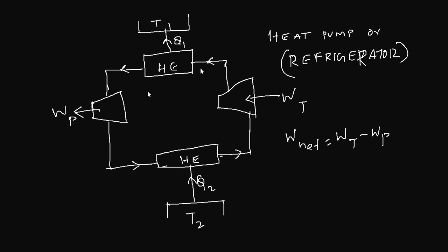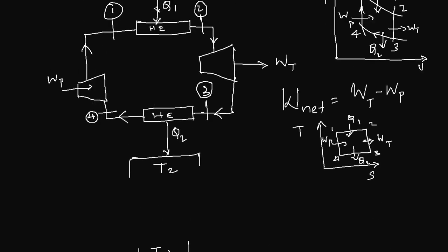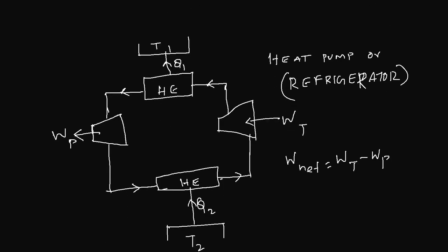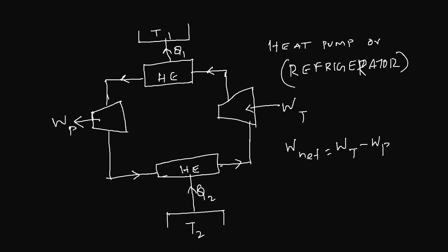Again, this is a reversible process, a reversed heat engine. This is the ideal case. This is not practically possible, but it is possible to produce a refrigerator and heat pump with losses, which means it is not reversible. Obviously there will be heat losses and friction losses, etc. But the concept of the heat pump and refrigerator originates from, and can be described from, the concept of the Carnot heat engine. So we have the Carnot heat engine and the reversed heat engine, or heat pump or refrigerator.